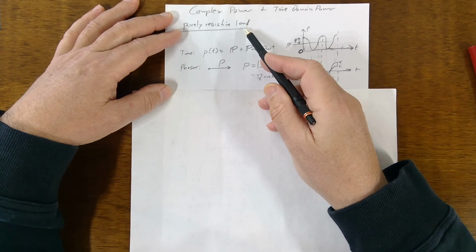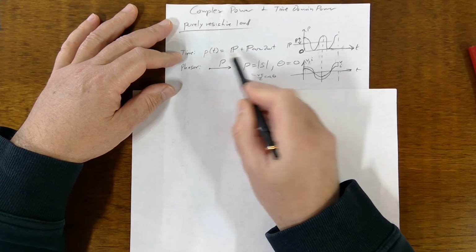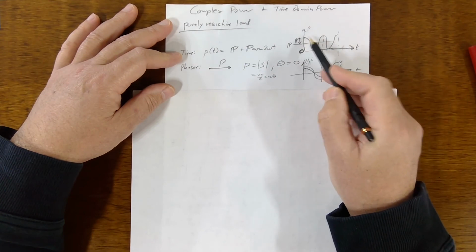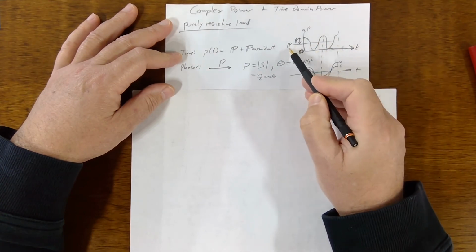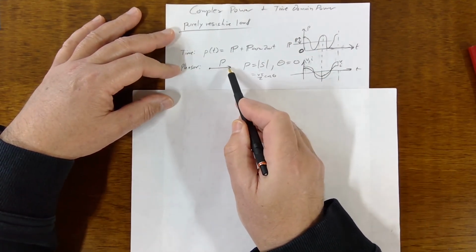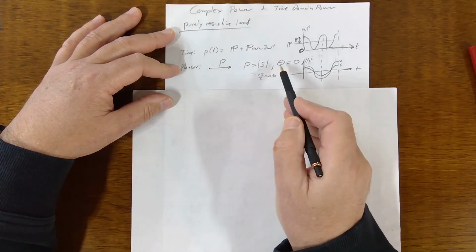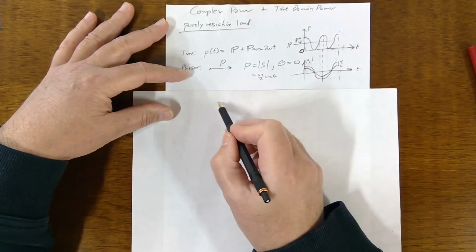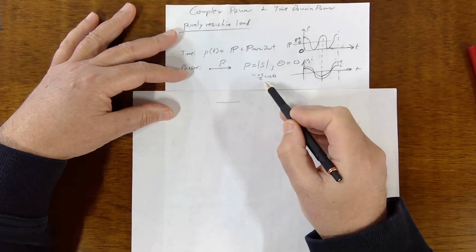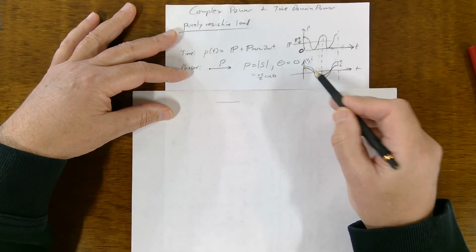So let's look at a purely resistive load in time domain. It's going to look like this. p(t) is this big P plus big P cosine 2 omega t. It's going to look like that in time domain, going from a max down to 0 and back up again. The average is P, big P. If you looked at it as a phasor, it would have no Q component. It would just be P. That means P would be equal to the magnitude of S. The phase angle is 0. The triangle is just flat. It's a line, because there's no angle in here. And V and I are in phase. They may have different magnitudes, V and I, but they're in phase.